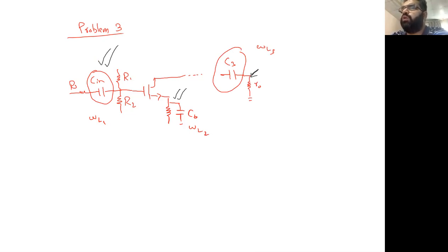So here, this is your V out point. Okay, and this point before the amplifier, you call it Vx, and you need to find just V out by Vx. That V out by Vx will have the C3 pole information. You have to get out the pole, doing something similar to what we just did. If you need, you can use the common small signal model and try to do the impedances and figure it out. So just give it a try. It should be easy if you understand 11.29, how we figured out the impact of C2.